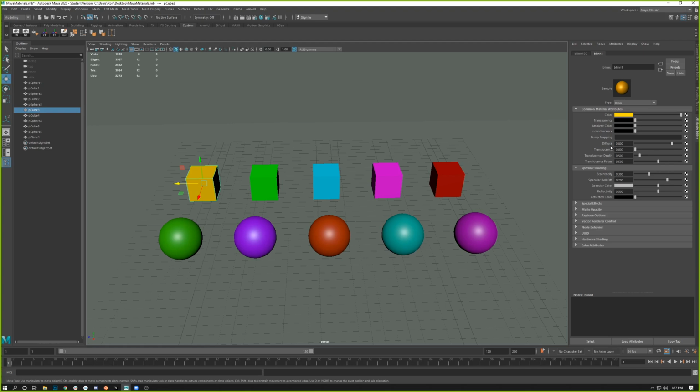And if you do take that time to think, oh, diffuse, I want it to get darker faster, your materials will adapt to changes in lighting in the scene. So again, in a complicated scene, instead of making something dark red because you're making a night scene, if you made the red car have a low diffuse but be brighter, then if the car was driving in the day or night, or if you used it somewhere else in an animation, it would adapt accordingly, and you wouldn't have to change the colors. So that's just slightly more advanced thinking on the diffuse, but by all means, like I said, you can just keep that in the back of your mind and play with it as you go.